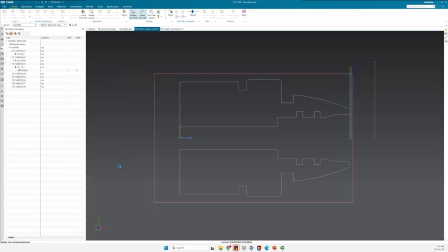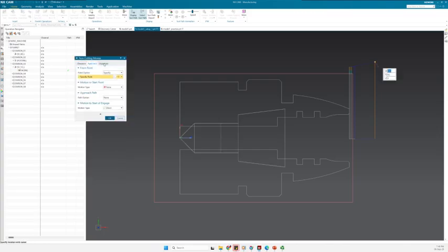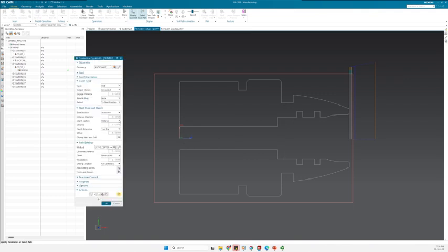Then I have the other parameters, for example, where are the cut and so on. So I don't engage with this one now. And then let's see if I have some other things. Yeah, so there is a depth of reference. So I want that from the tool tip, so the tip of my spot drill, that it goes inside the part 3 millimeter, for example.